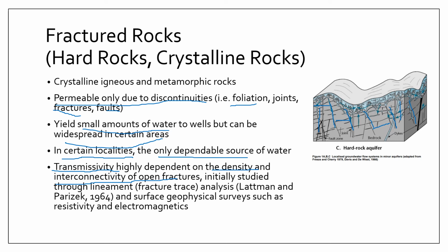Okay, and normally you only get fault gouges when you have faulting in an area that is intersecting typically shale formations or highly weathered formations. Okay, so when a fault intersects those layers that contain silts or clays, then you can have fault gouges in your faults.